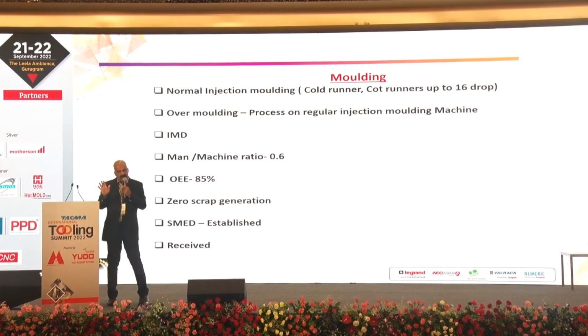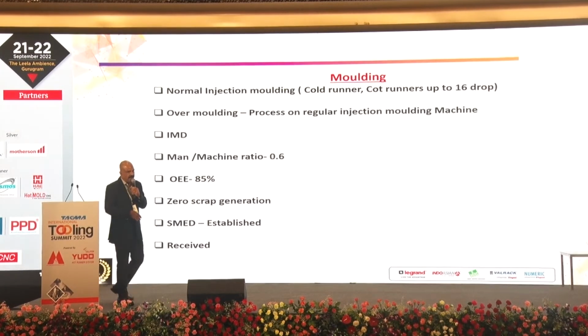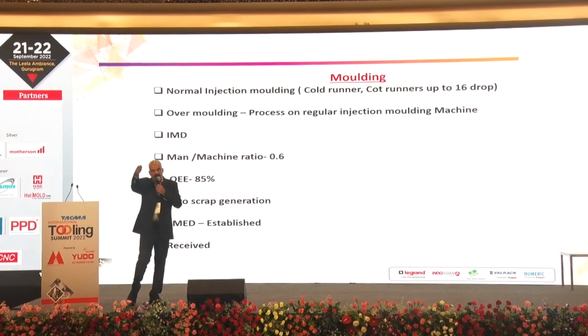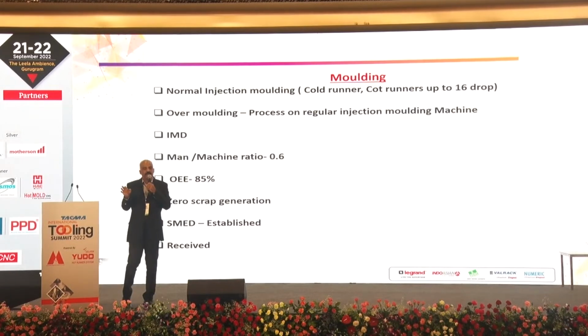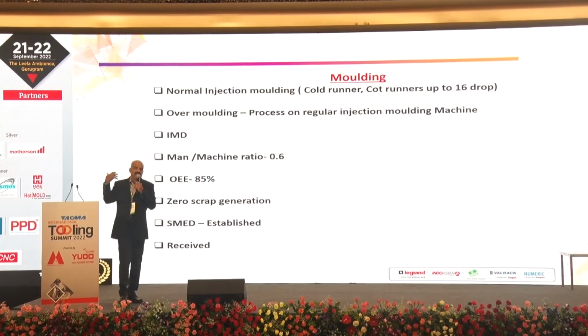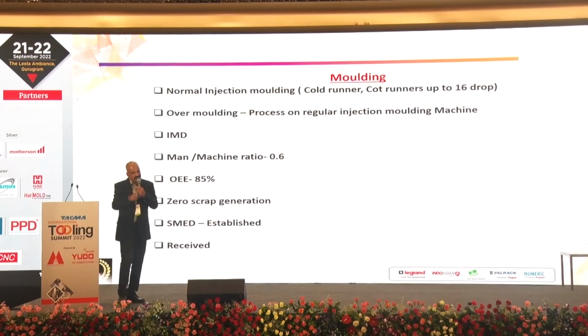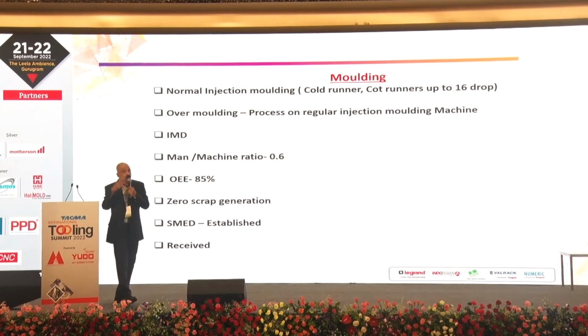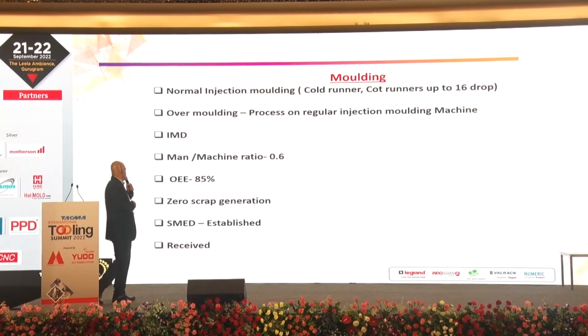So we're using 100% regrinding, online. It is not offline, it is online. All the machines should have the backup of a grinding machine. It is collected from the mold, immediately put on the grinder, and sucked in by the defined ratio, which is approved by R&D. If 15% is allowed, the machine will not accept more than 15%. The balance will go to the next mold. So tested, then only it is approved. Otherwise, some components we don't use it, because technically it's not allowed to use regrinding.